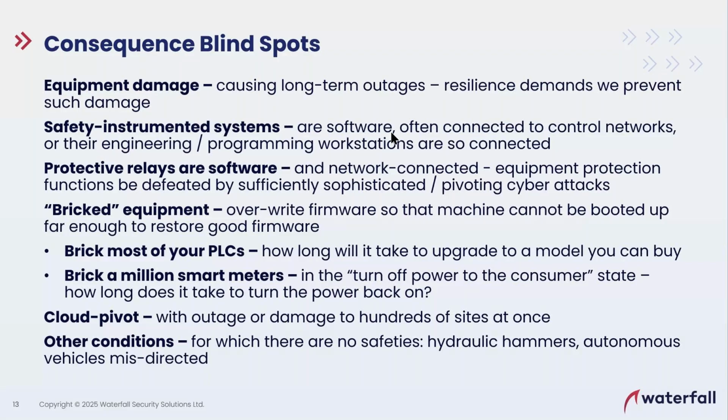The flash burns out after about 1,000 writes. Now, it's not just that you can't boot the device, it's that the hardware is burned out. Even if you take the device apart and look at the hardware and try and stick firmware back onto it, you've got to replace the flash chip. What if they burn out 80% of the PLCs in our facility? Do we have spares for 80% of the PLCs? Most of us don't. Most of us have 10 to 20% spares.